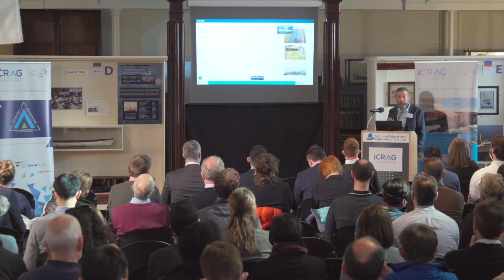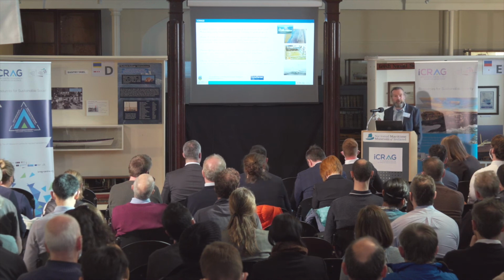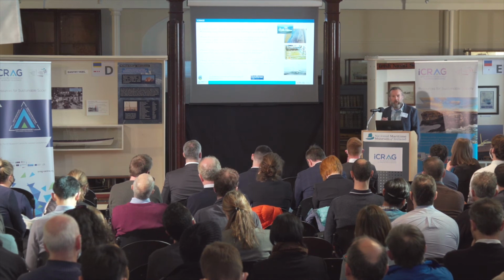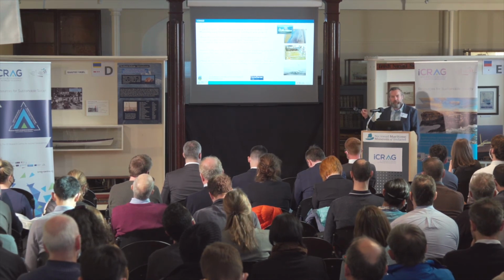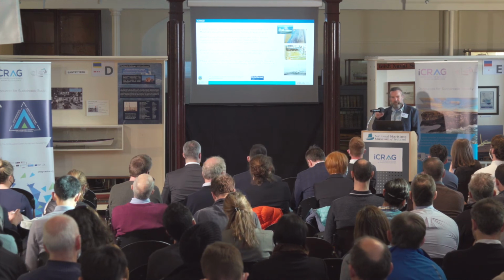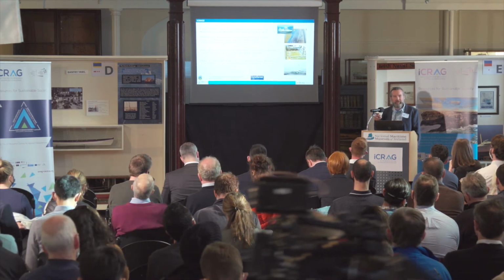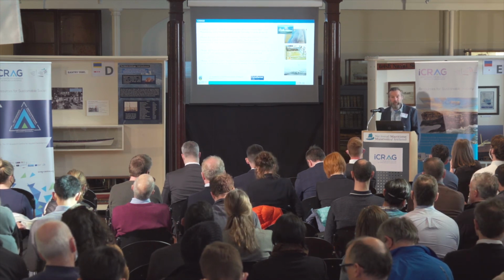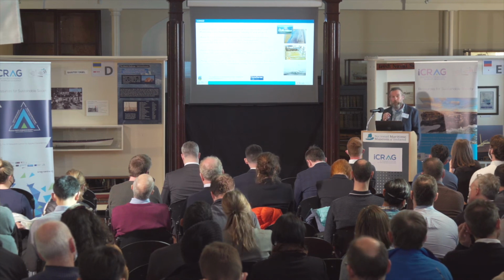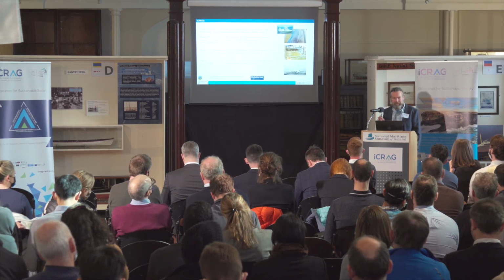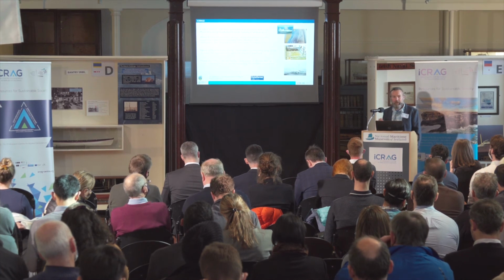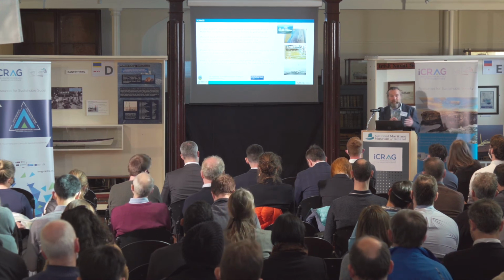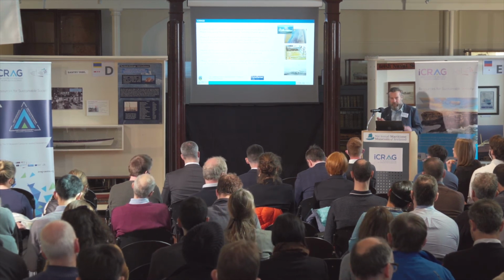That's a good question. So, resolution is comparable to using hydrophones. We lose a little bit on the high-end frequency, but not what would affect the resolution, because we're looking at shear wave profiles with depth. So we're still able to record the high frequencies. The systems are incredibly sensitive. You can record up to kilohertz with them. Obviously, we're not. We're talking about the tens of hertz range, so that's fine.